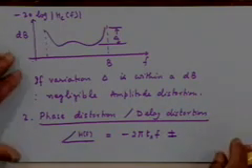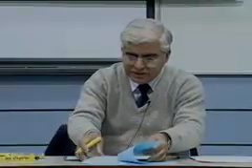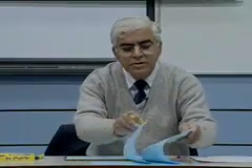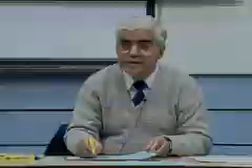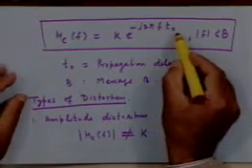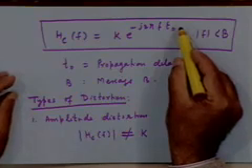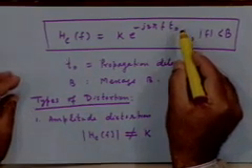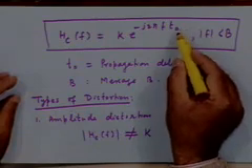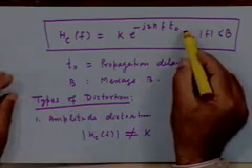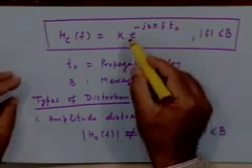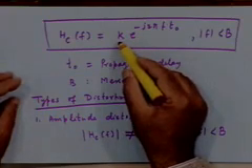If you go back to this equation that we were looking at, right, if I put a e to the power minus j m pi or e to the power plus j m pi, where m is an integer, this will be a constant value equal to either plus 1 or minus 1, which could be absorbed in the attenuation factor, right.